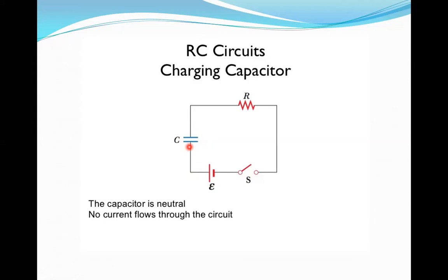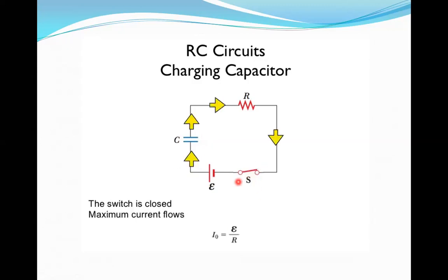Now after the construction, let us understand the principle of this circuit. Earlier the switch S was open. Now what will happen when the switch S is closed? You can see the current flowing in this particular direction, through the condenser. When this switch, which can also be called a Morse key, is closed, the charging of the condenser takes place until the potential difference across the plates of the condenser becomes E.